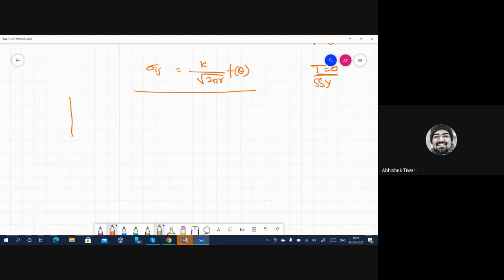T stress is 0 simply means that the plastic zone is very small. Okay. So this is my object and I have a plastic zone which in mode 1 looks like a butterfly. And this zone is very small. Okay.